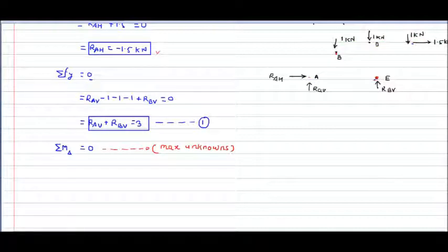Okay, so now suppose I'm going to use point A as a fixed point. I have already discussed, or told in my previous lectures also, that whenever we have to calculate this moment, always keep these two things in front of you: one is sign convention, and another, the formula for moment, which is nothing but force into perpendicular distance.